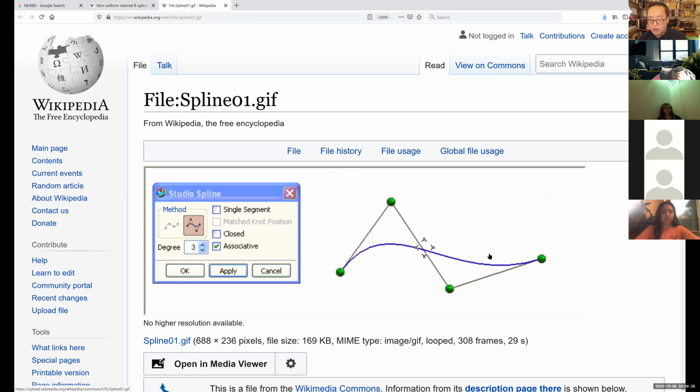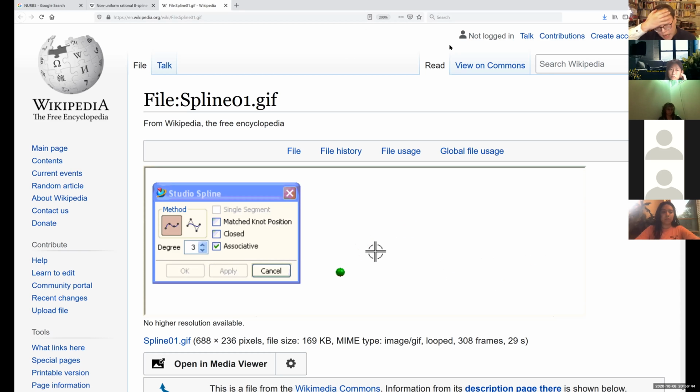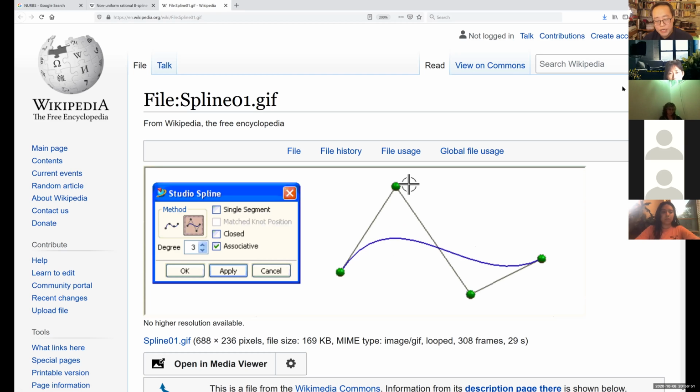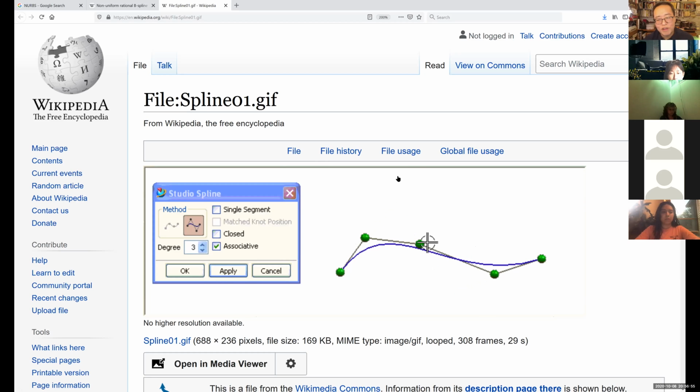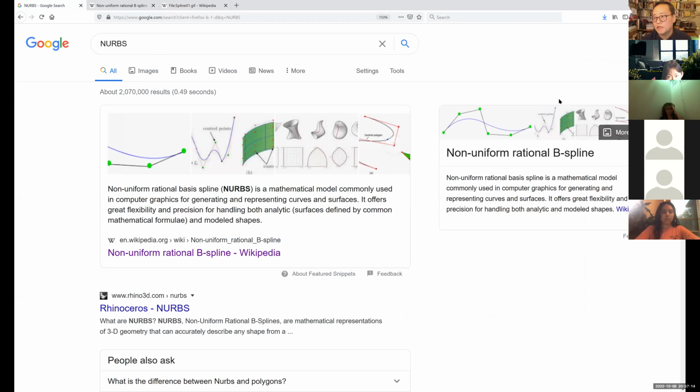So the CAD software being able to handle NURBS geometry is basically saying, hey, if you want to do car design or product design, like a laptop computer from Apple, infinitely smooth, we've got the math to back it up. That's what NURBS is. Packages like Maya, Alias Studio, and Rhino are NURBS modelers, so they can handle that. SolidWorks, yes. Onshape, yes. However, they don't let you directly sculpt your surfaces, because they're engineering CAD software. You have to go through profile curves drawn up in the sketches. That's the pain with it. Direct sculpting is not really a thing. Fusion does that to a certain extent, but that's the NURBS aspect.